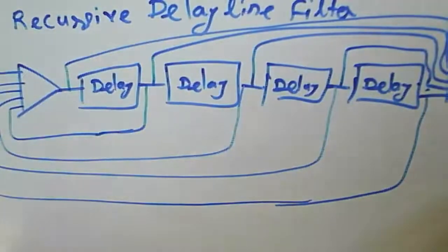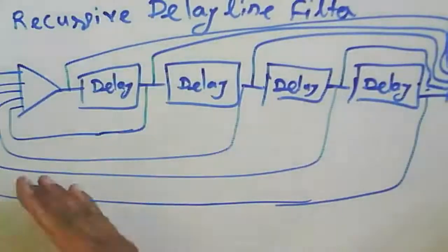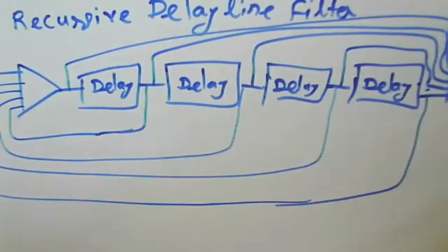So these are the uses of this delay line filter. And again a delay line filter depends upon the frequency response it will work with. Generally it will work at given pulse repetition frequencies. So what will be the frequency response of the pulse generated across the output of the filter from a single particular pulse through the given feedback? Based on that, we can consider the clutter attenuation.